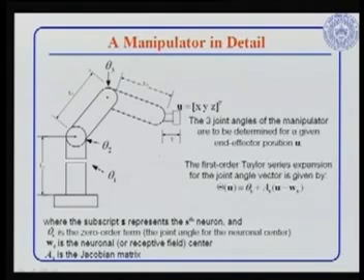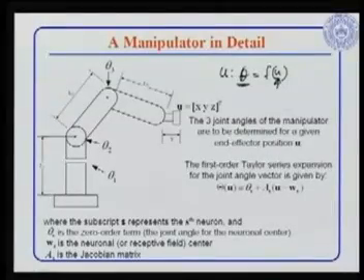So what we are trying to do is find from u a map, so theta is f of u. We would like to find out what theta is given u, through learning. Now, one can easily use the inverse kinematics of this manipulator and find it out. But this principle is different. We do not want to go to the manipulator inverse kinematics, and simply learn. I want to find out what theta equals f of u. The objective is just a curiosity about how powerful learning can be. We can ignore the inverse kinematics of an actual model and still reach any point in the robot workspace.